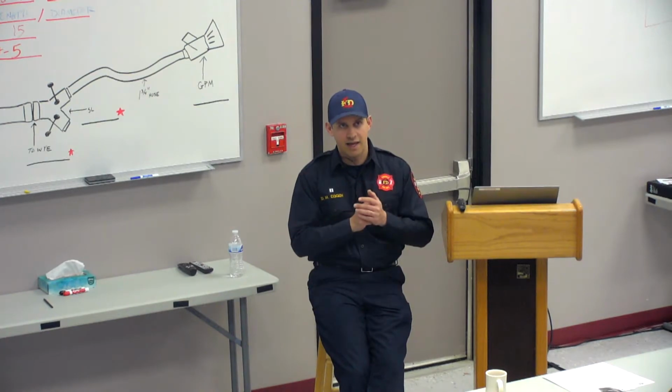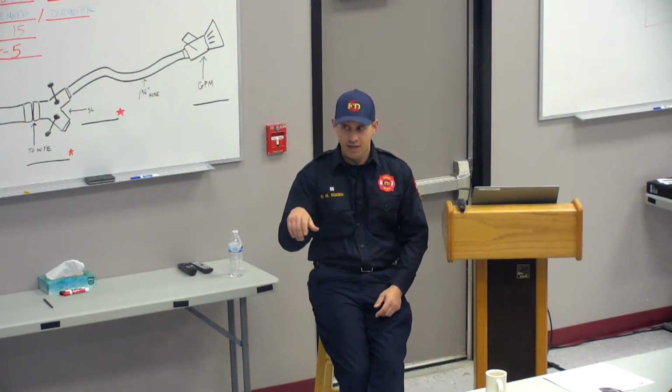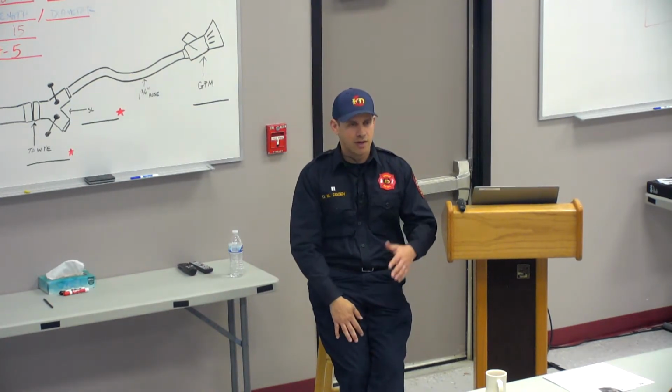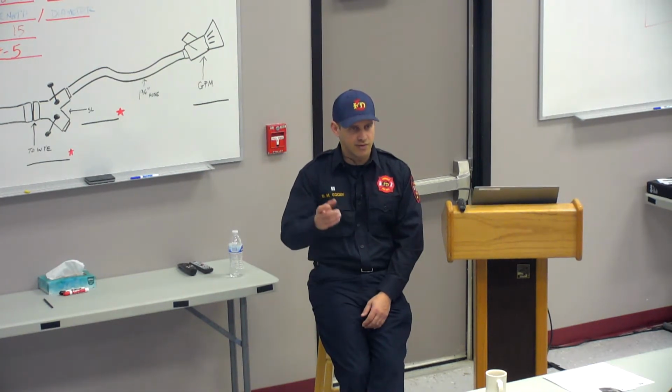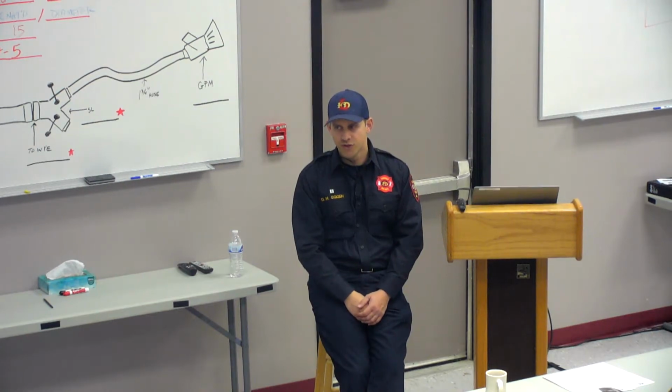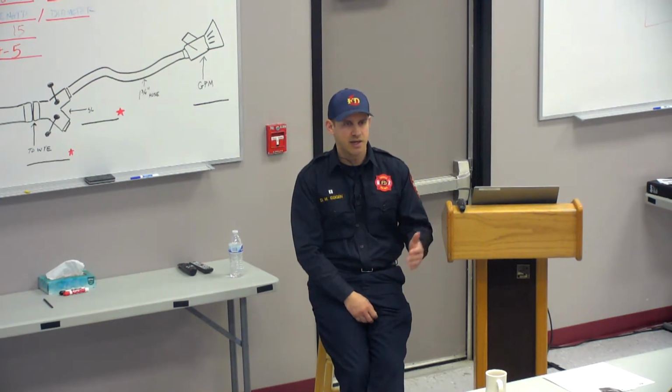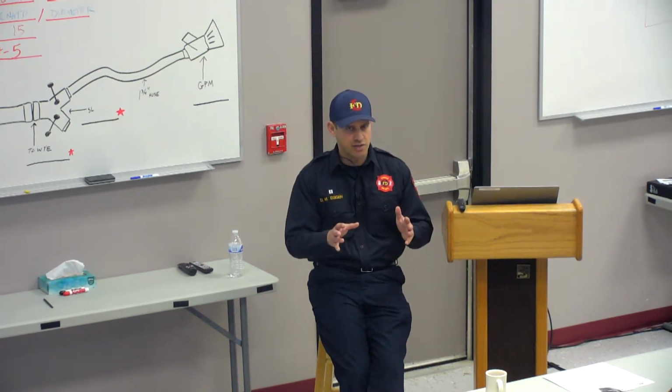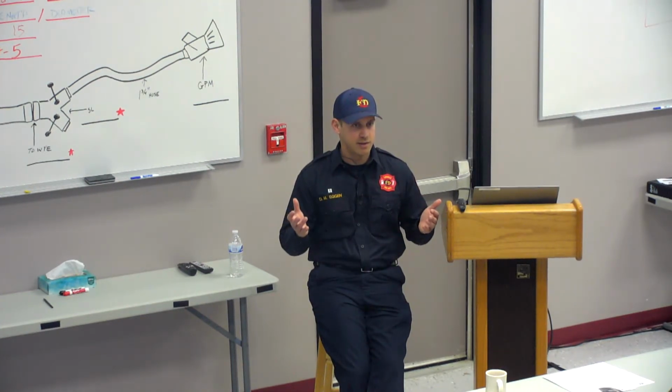But something that has been going on is people will be coming in the morning. We've all heard the set it to 150, make sure it works, right, and leave it there. There are some different theories on that. Some people will say if your longest cross lay is 170 or 300 feet, that you should set it in that 170-ish range because that's what your pump pressure would be for that lay. Some people set it at 150.